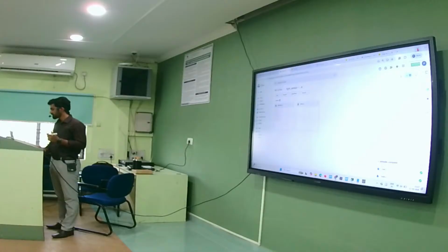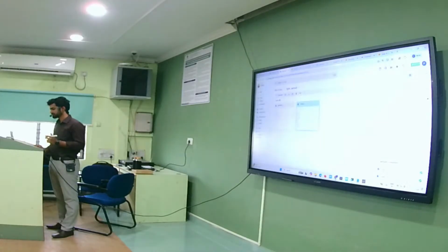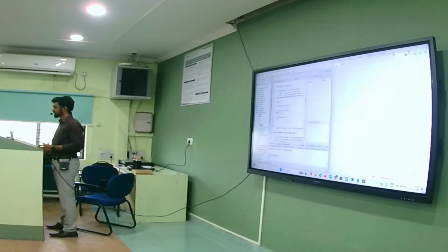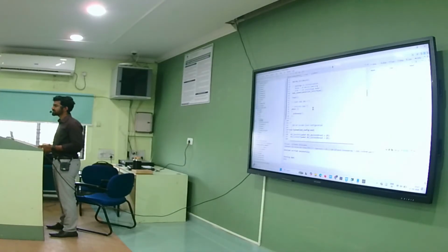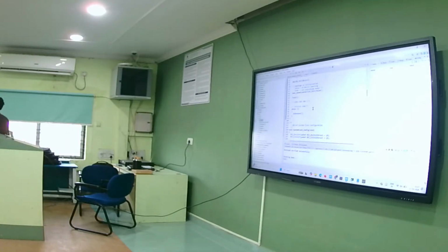Okay. You can download it, and add it in the main.c section. After adding, just check what changes I have made here as compared to the data logger code. Previously, the functions void log and void fill buffer were there. So I added three functions now, including void fill buffer. So, total three functions.